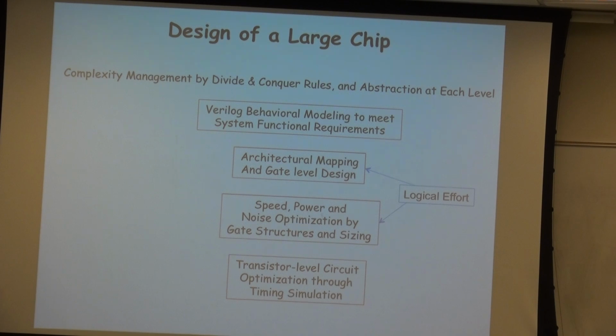What is the advantage of using it at all? The advantage is that the other adders need some extra logic. Nothing comes free. In a ripple carry adder, you are just connecting the C out of the previous stage to the next stage C in, right? So just one line. But in other cases, you need some extra logic. Okay, we'll talk about that actually.